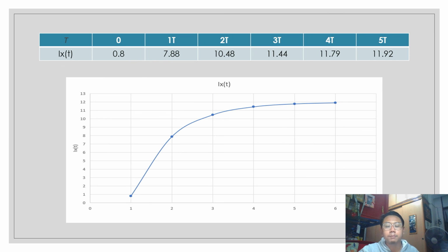So just that from me. But before that, the important things in this chapter contain two circuits, which are the RC circuit and also the RL circuit. The difference between these two circuits is that the capacitor will open circuit and the inductor will short circuit, and the difference is in the equation. And the last one, when we want to sketch the graph, be careful of the negative sign. If the value of Ix(t) is negative, the graph will go to the negative side.